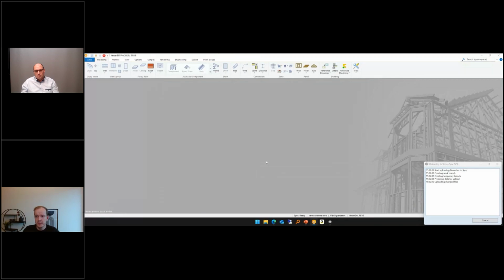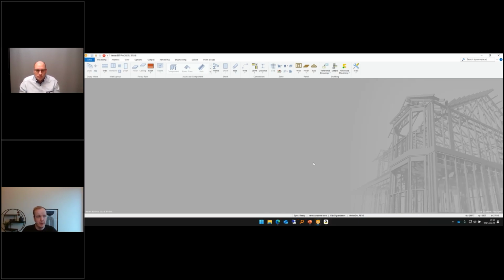So now it will create the temporary branch. It will basically compare the sync copy and my working copy, and then upload the changed files, which are different basically from the local selection. So now it informs me that uploading the demo house to Sync was successful, and it took around 19 seconds. And then you may now close this window. And of course you can close BD while that window is open, so you don't have to keep BD open.